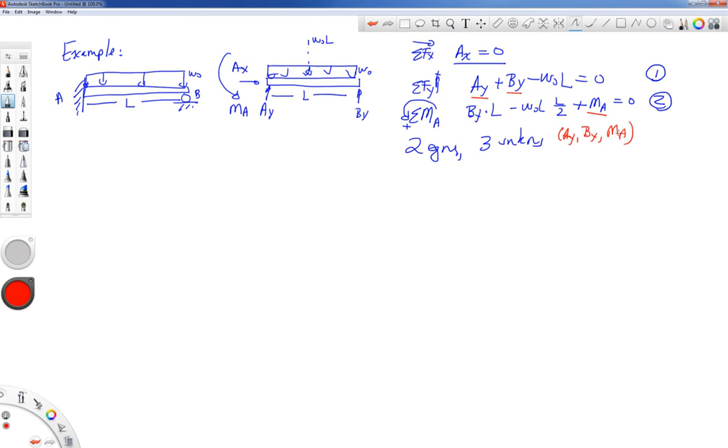So the next thing we need to do then is to look at our geometry deformation or load deformation equation. We're going to start with the load deformation equation. Let me switch back to blue. I need to find the slope and deflection equations of this beam. This works just like any of the other beam problems that we've worked. I'm going to cut this at some arbitrary position X. I'm going to draw the free body diagram.